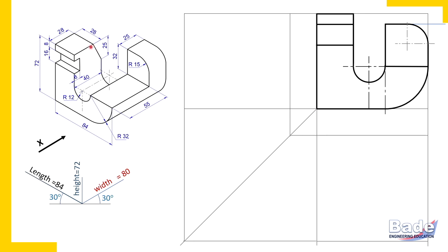Remember, if a surface has an edge parallel to the width axis, tell me, in which view does width not appear? Front view. It means in the front view this surface does not appear, in the sense it appears a line. So this surface appears a line here. So all edges on this surface appear on the same line. So this edge is already there. This vertical edge is also already there. Now what I am telling you is that a corner is formed by three edges. So where is the third edge from this corner? So listen, check all other corners of this surface.